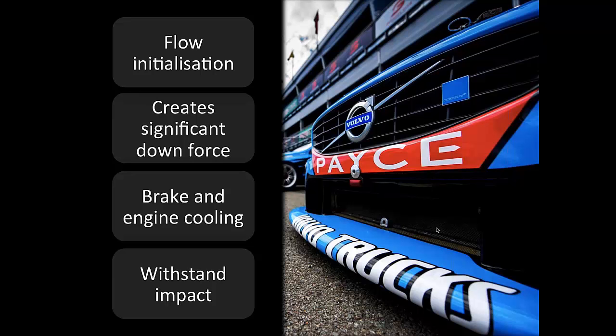Sometimes if you don't, and I saw this on one of the early prototype models, our bars were a bit weak in the splitter department, and you get what's called porpoising, where you get a dramatic change in downforce as the bar closes in on the ground, and then you'll actually hear a quite terrible grinding sound when the car's doing 260 kilometres. You have to make some changes to your composite layout.